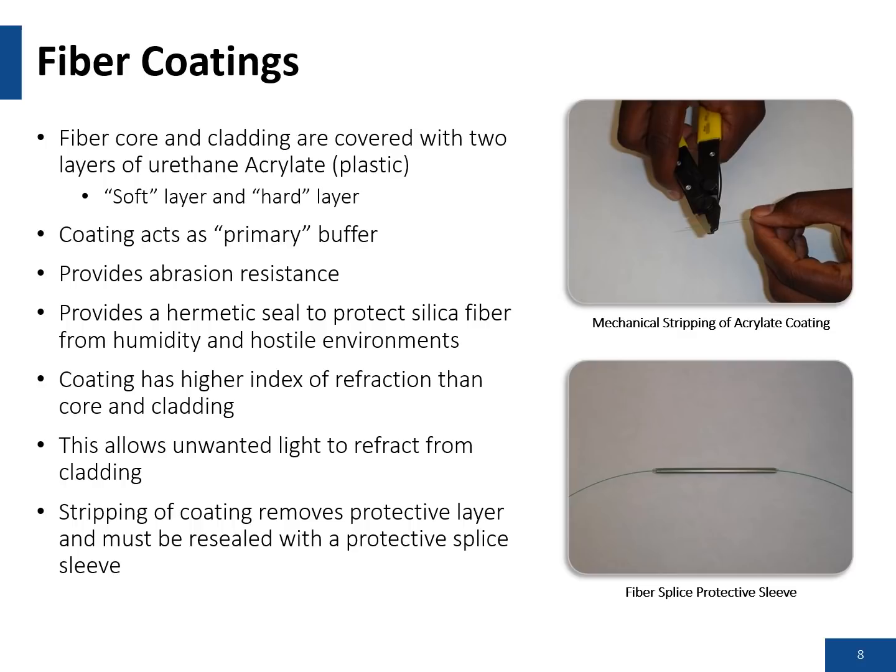When you're doing the splicing process, you have to strip the coating to remove the protective layer. This has to be resealed with a splice protective sleeve.